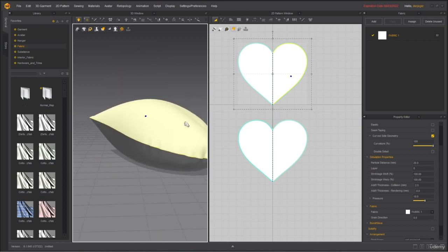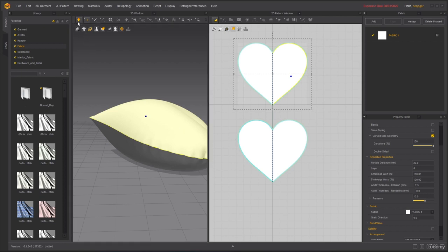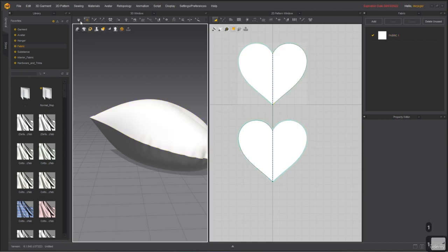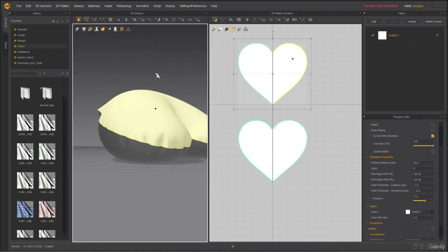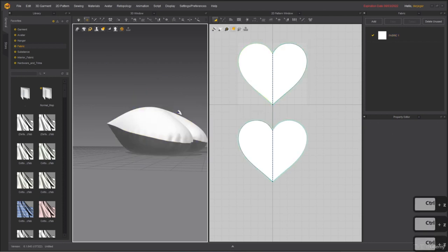Now, super important, whenever you're using pressure, you want to make sure that the pressure is the same, or I mean opposite, but in the same amount for both sides, because if you change this just slightly, maybe if this is like 11, what's going to happen is this thing's going to start floating around, and especially with lower numbers you see this a little bit more because there's going to be more pressure on one side than the other. So you always want to keep the same pressure on both sides.